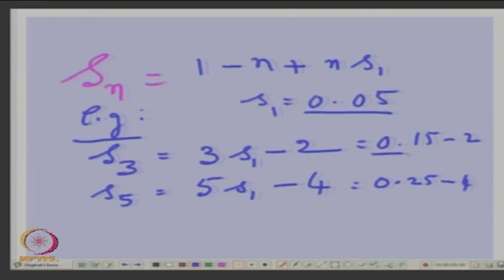This is nearly 2, this is nearly 4. So, rotor currents will have 100 cycles, maybe 200 cycles. So, there will be high frequency currents in the rotor because of the harmonic fields. Okay. If harmonic fields are absent, you have no problem.